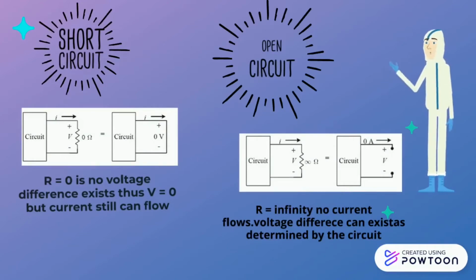Open circuit voltage is the difference of electrical potential between two terminals of a device when disconnected from any circuit. There is no external load connected. No external electric current flows between the terminals. Alternatively, the open circuit voltage may be thought of as the voltage that must be applied to a solar cell or a battery to stop the current.